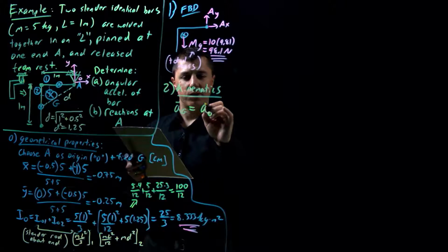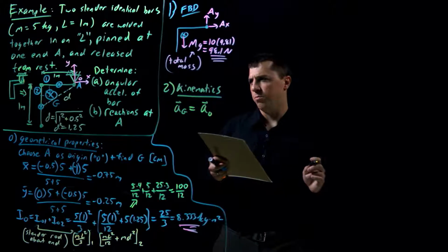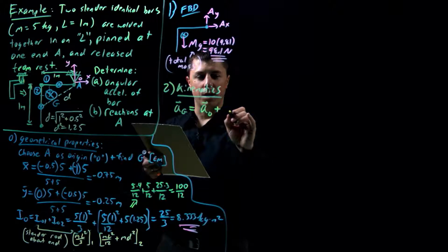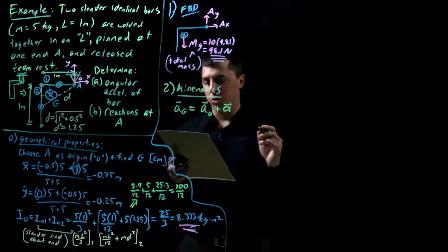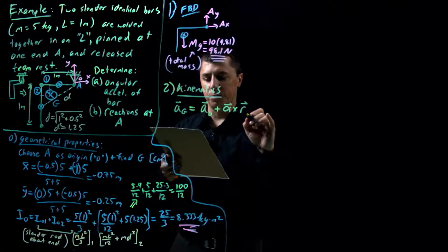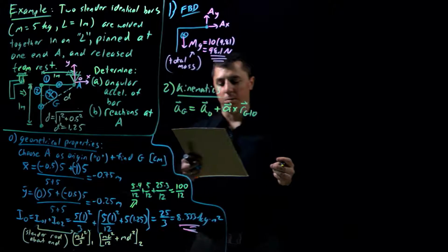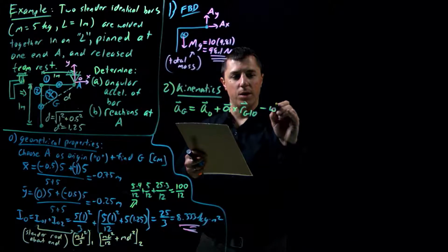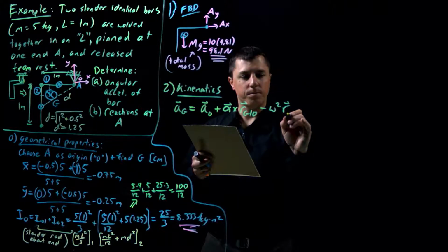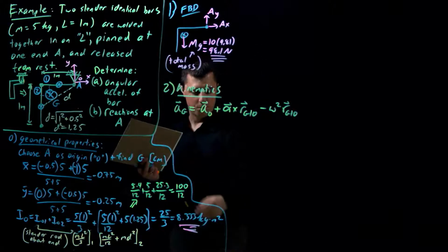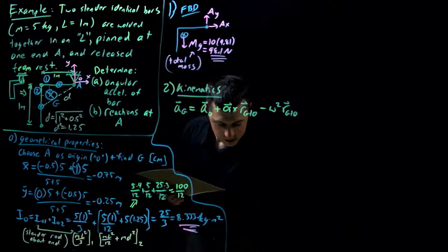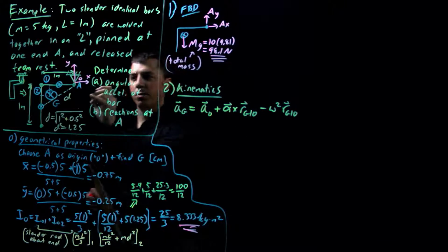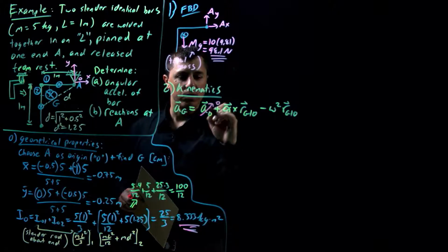Okay, so let's write it as the acceleration of the origin, or we could have put A there as well. So this is going to be the acceleration of the rigid body crossed into the relative position vector of G from point A, or the origin of the coordinate system, minus omega squared r. There's that position vector again. Now we ask, can we cancel anything out here? Well, this is a fixed point, right there. So that's 0.